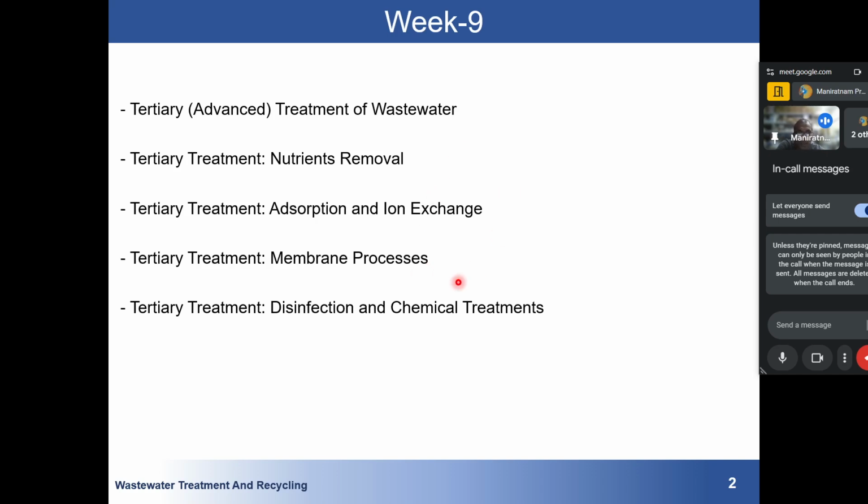If you recall, the drinking water parameter limits have been set in India, and all the limits are given in IS code IS 10500 2012. In there you will find the limit of each and every water quality parameter. Each and every water quality parameter should meet those standard values. In that way only, the water can be drinkable.